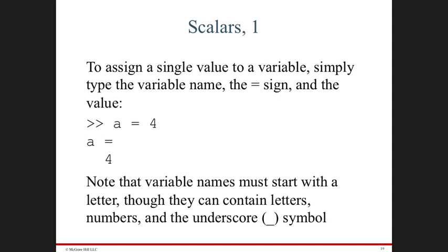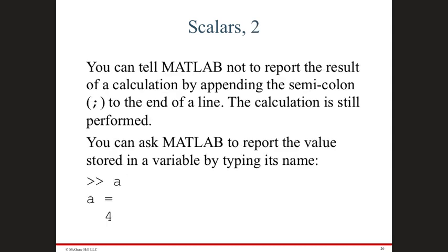But if you have the variables window to the left side or to the right side, depending on your layout, you will see a variable called A there, and if you click on it, you can see the value 4 stored in that variable, and that variable stays with you as long as you didn't clear the variables of MATLAB. There's a command called clear, and then you can clear a particular variable by name or clear all. So you can clear all variables stored in MATLAB.